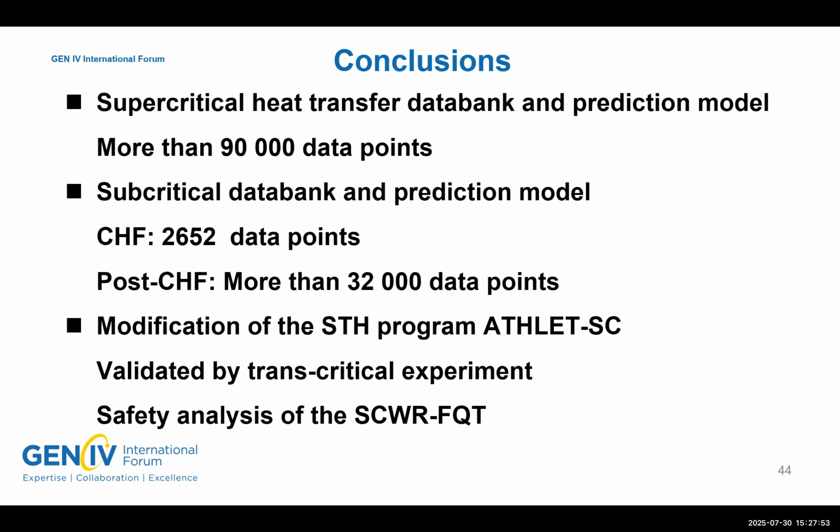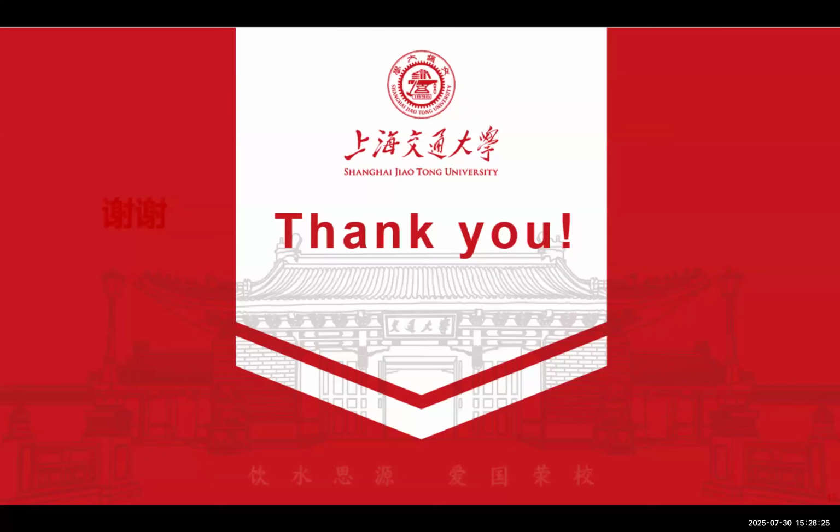And also, if you want to perform the transient analysis, you have to modify the system codes, and then with this code, you can validate by the transcritical experimental data, and also you can perform some safety analysis or some hydraulic analysis of SCWR or the fuel rod loops cooled by the supercritical fluids. I think that's it, what I want to show you. And thank you very much for listening.